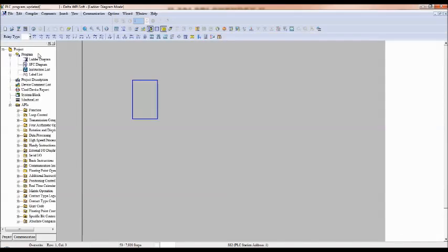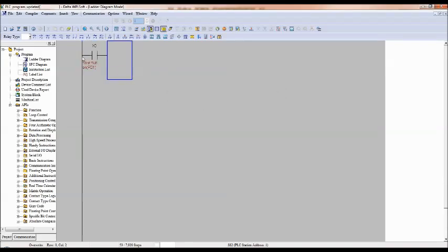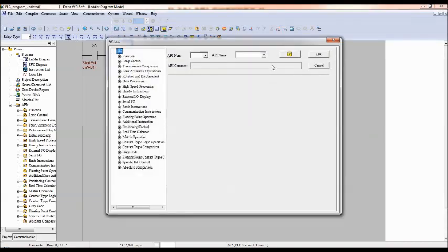So I will take the start button. What should happen? First of all, valve 1 should open for filling, and the stirring motor should be on. I explained in the previous videos how to use multiple outputs in parallel. Using that video as reference, but here I will use the set and reset function. So F6, and here you can type the set instruction.